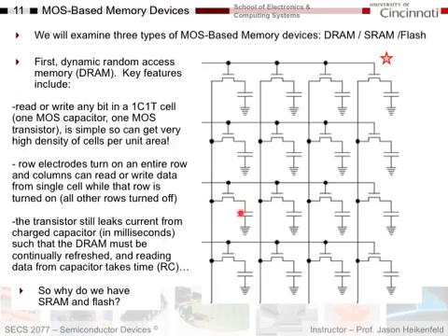And so that's pretty long, but that's still short enough that every now and then you're going to have to refresh all the 1 and 0 states on all these, because if you don't, they'll all leak back to 0. So you have to constantly refresh DRAM, all its data values for these capacitors, from time to time, which is a bit of a disadvantage. However, it's pretty simple. That's one of the big advantages of DRAM. You can see this is probably pretty easy to make.